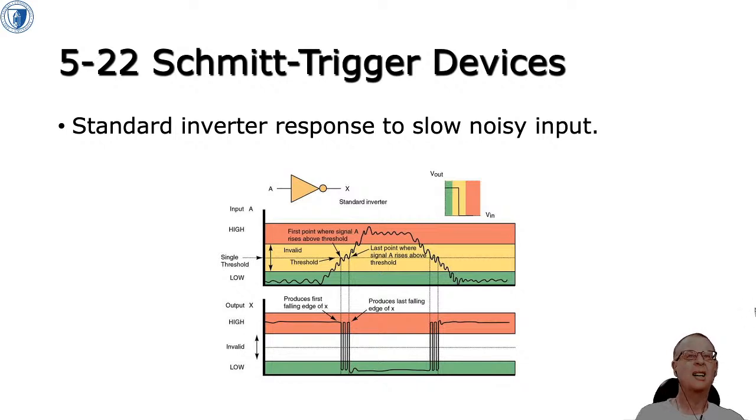If you've got a single threshold, like in the middle diagram here, and you've got your noisy signal transitioning from a 0 to a 1, the green is the 0 level and the red is the 1 level, but we've only got a single threshold. So on the rise, you get chatter between the 0 and the 1 because of that tiny bit of noise around the threshold. And on the downside, you also get that chatter between the 0 and 1 because you're oscillating around that single threshold.